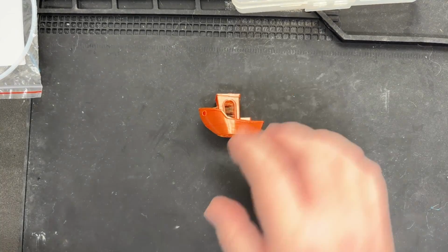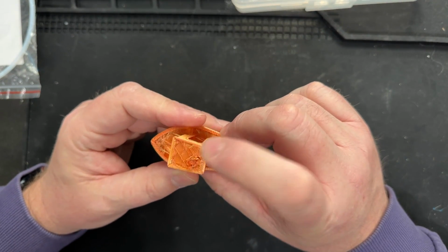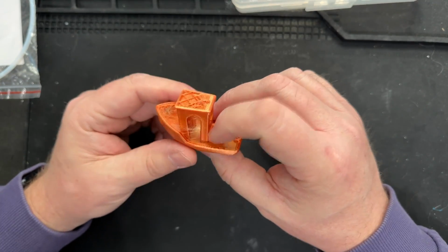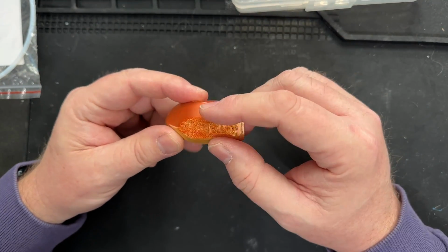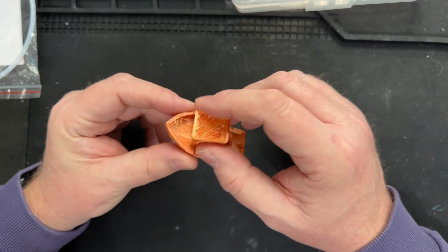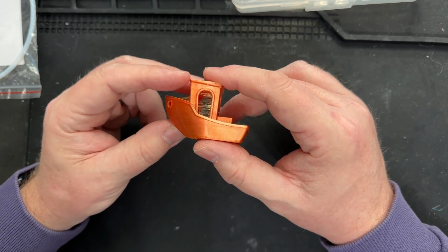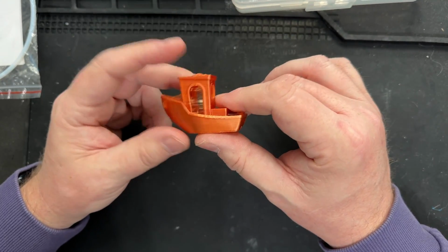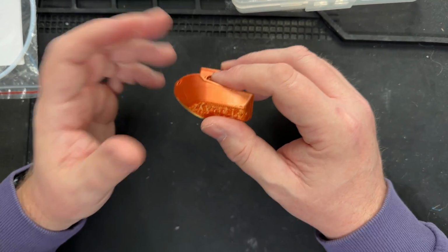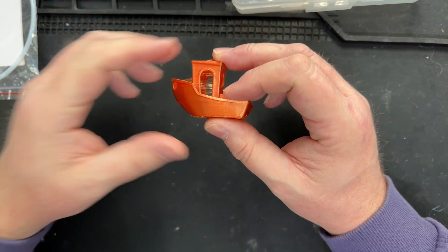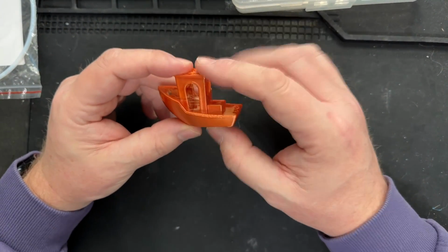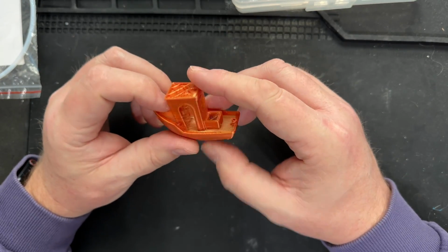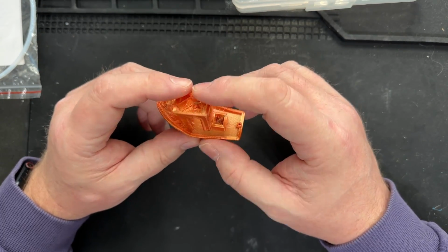As you can see, I finished the Benchy. Now I will point out that the print failed here at the top. Actually got knocked over. Most of the time with the Benchy, I print with the brim. This time I did not. Also, I noticed the printer didn't run a bed level before it did the print. Normally, when I do a print, I prefer to always run a bed level before I print. So I need to add that to my start code. You notice there's a lot of stringing here, so my retraction's not correct.